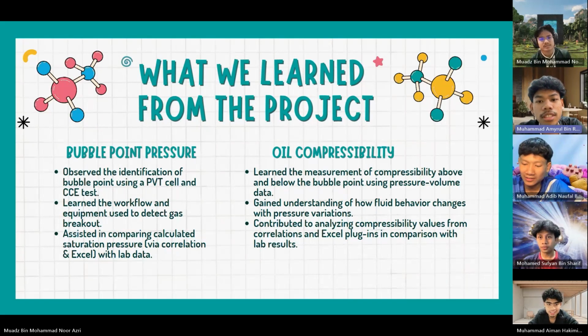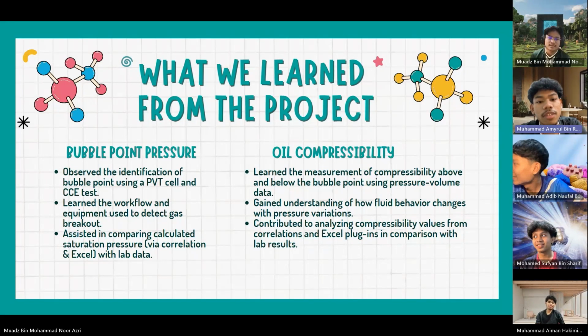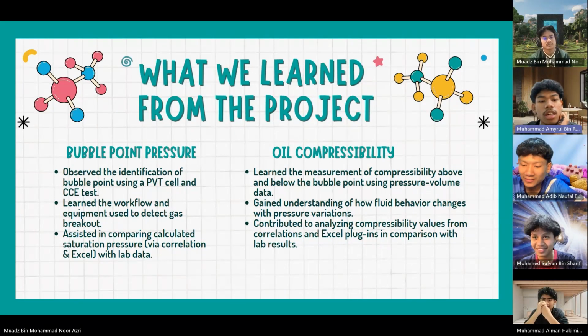For the next part, what we learn from the project. First of all, for bubble point pressure, we can observe the identification of bubble point using a PVT cell and CCE test. We also learn the workflow and equipment used to detect gas breakout. Another, we can assist in comparing calculated saturation pressure via correlation and Excel with lab data.